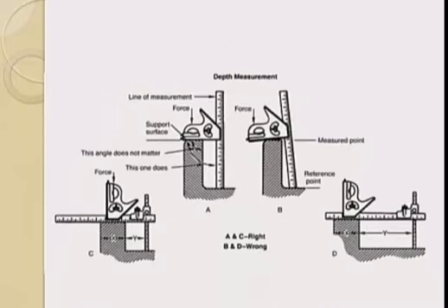You can also use it for depth measurement. Notice in this illustration that B and D show error by using the device incorrectly. You must make sure that the rule is correctly in line with the measurement.